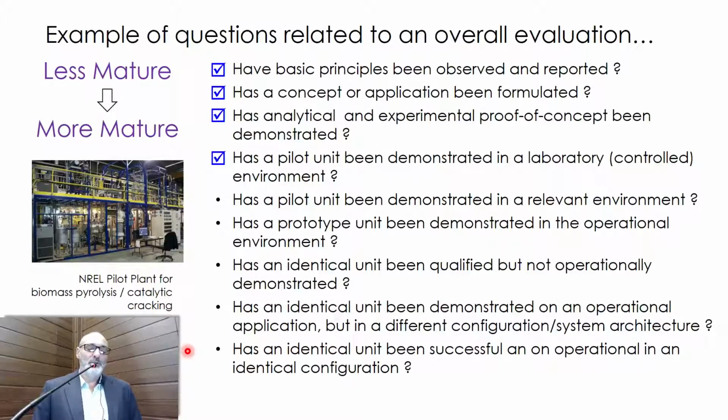Has a pilot unit been demonstrated in a relevant environment? By relevant, I mean you start experimenting with the actual conditions that you're going to find in the field. You can do this in the lab. You can contaminate your feedstock just to test. I used to do this a lot. I add sand to my feedstock, to biomass for instance, or mix with residual sucrose, to see what's going to happen in the process.